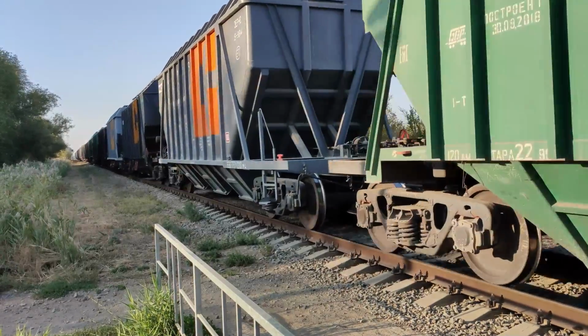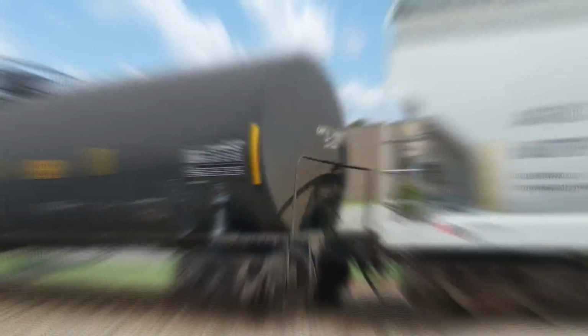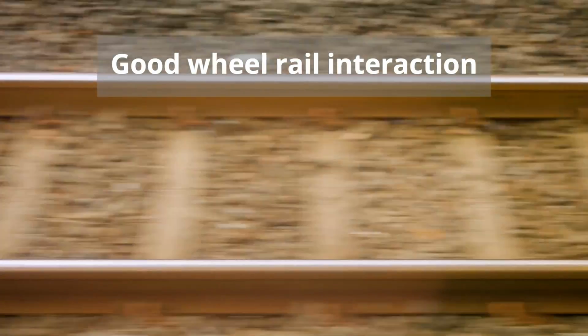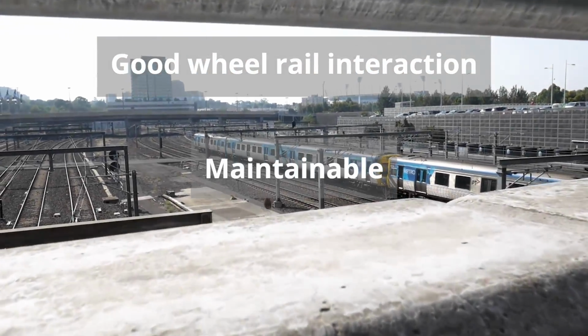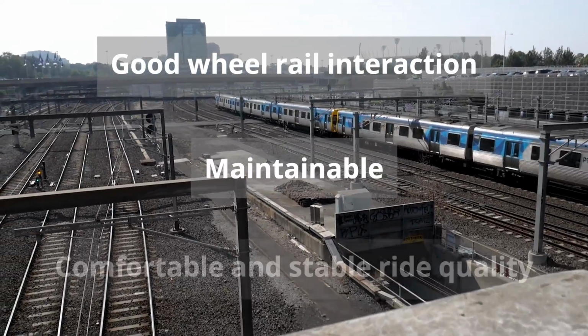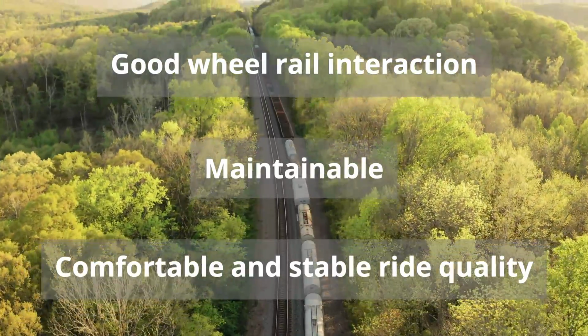Good track geometry design is important for a number of reasons. It ensures good interaction between wheel and rail. This minimizes wear on the rails and the wheel along with other components. It is maintainable after installation, to ensure the ongoing safe passage of trains. It provides a comfortable ride for passengers and stability for freight loads.